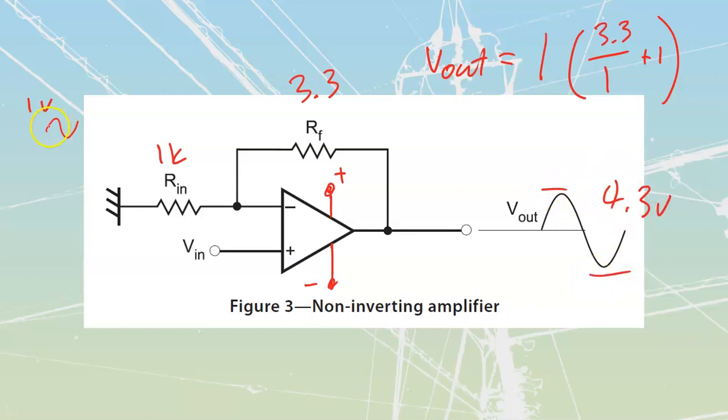The important thing to note as well is that this is only going to amplify the physical magnitude. It is not going to change the timing. So in other words, this is what the waveform looked like on the input side. It was just a tiny little waveform, peak to peak, but we were able to get a much larger value out. But where it crosses the x-axis, the frequency of my input is going to stay the same. It does nothing to frequency. It only amplifies our value of voltage.